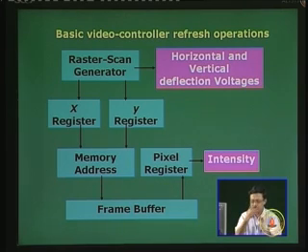Okay. So, at that particular point the deflection voltages of the horizontal and vertical deflection plates, or it could be the solenoid, the magnetic coil, which controls where the beam position currently is, is dictated by what memory you are accessing at the frame buffer. That is number one. And number two, what should be the strength of the electron beam, whether it should be switched off or switched on, the intensity of the beam. So, these are the two outputs of the video controller which go into the monitor. The monitor needs these two inputs from the video controller to guide the beam and switch it on and off at a particular intensity. I hope it is clear.